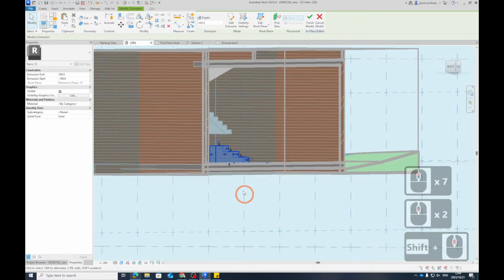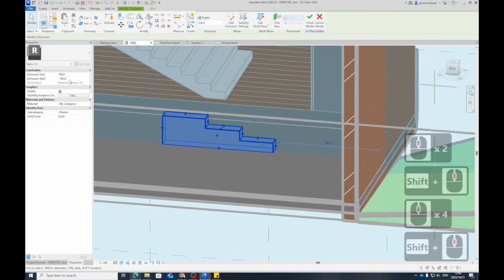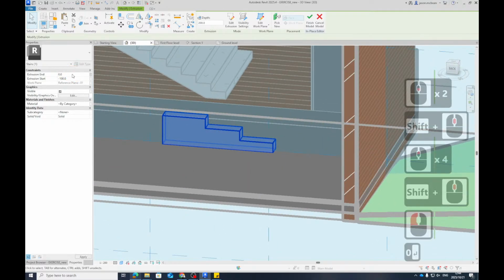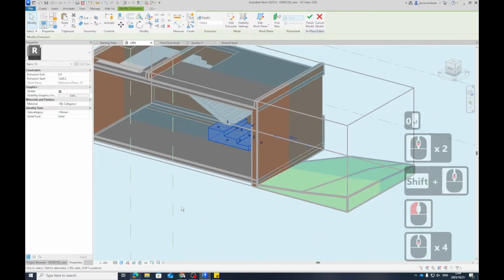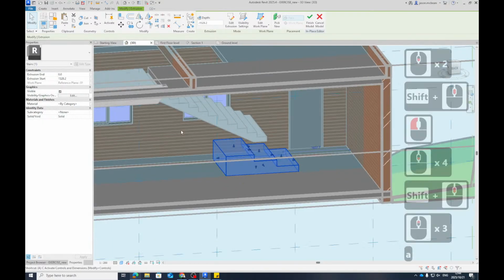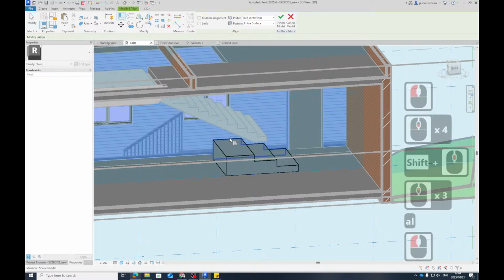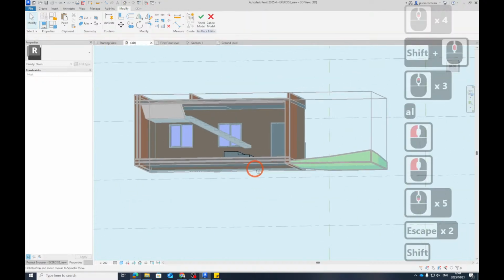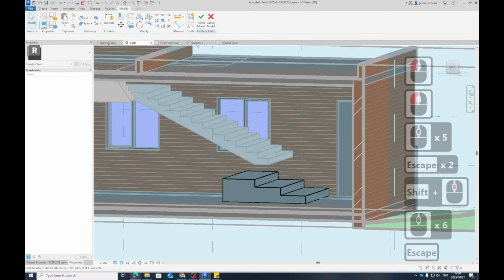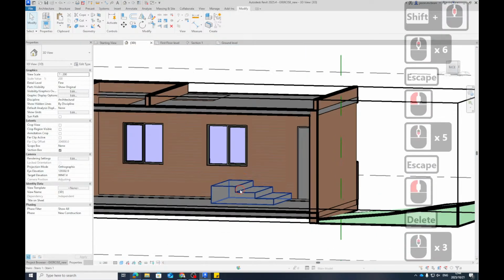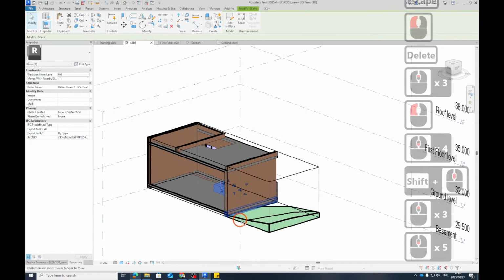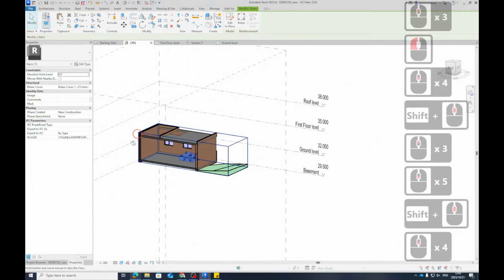But now, if you look what I'm doing there, it will end at 0, so it'll be flush onto that. And it'll start at minus, see what it's doing? Yes. But I'm going to align to the wall, so align to there and align to there. See what it's done? Okay, yes. Go finish. Now, I'm going to delete this for now. This stair, we've gone up 3 rises already. So I'm going to create a new stair.